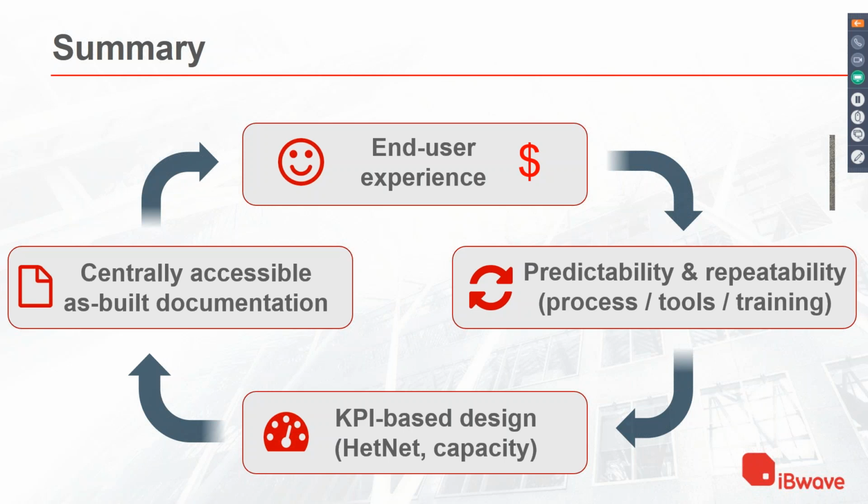Okay, so first of all, maybe if I look at, because we have 2 different technologies here, so I'm not sure I'm addressing the question, but if you look at LTE, first of all, LTE is obviously licensed, so the bands are well controlled by the operator. But then it's important to do the RF walk, as I mentioned before, to really understand what the RF environment is, because different carriers will have different approaches, right? Some might use different bands for the micro network and for the indoor network, some might use the same band. In the latter case, I think interference is particularly important.